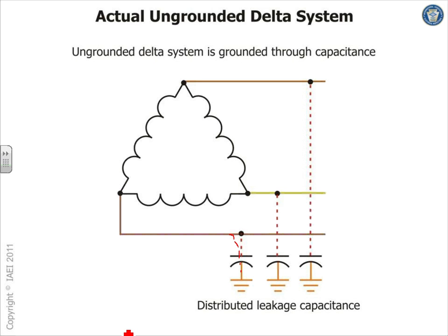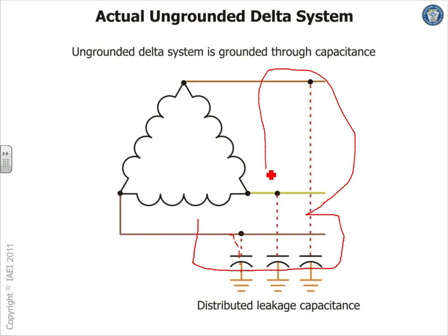But if you go into a system that is ungrounded and you measure the voltage, you'll get a fluctuating voltage because there is a capacitive impedance that ties the phase to the ground, right? Keep in mind there is a conduit where all these conductors are in. So what's a capacitor?